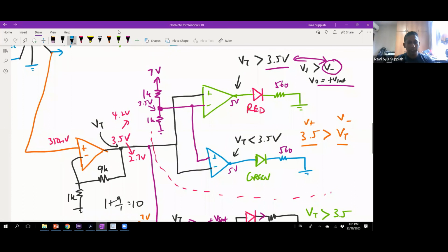Okay, I mean, in reality, let's say you are going to do a project where you need to do something like this, the best way would be to just take the signal and pass it to the A to D of your microcontroller, okay, and then do all the processing over at the software side. Okay, so that is always the easiest way, because like I said, most systems nowadays are all moving towards the digital implementation or solution, which means almost every device has some processor, some microcontroller that can do this for us.